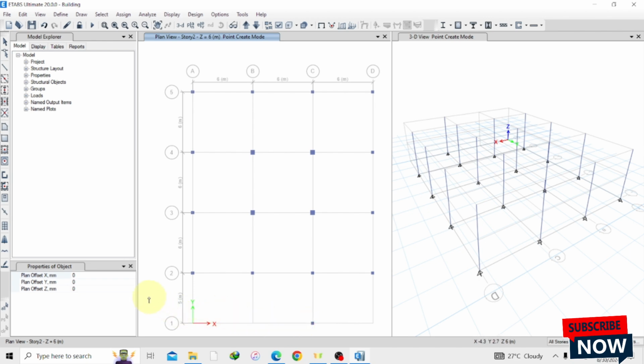So we need like 3 meters in the x direction. But looking at our unit, it's in millimeters, so we have to change. So we have to just input our values in millimeters. So negative 3,000. And hit enter on the keyboard and just come and select this point, and you see we have